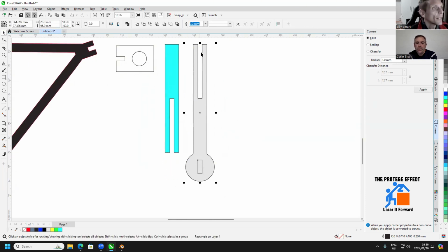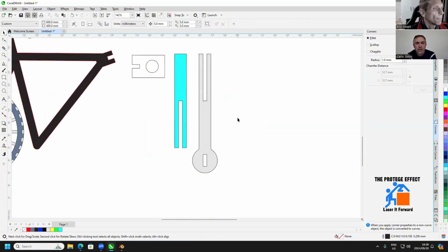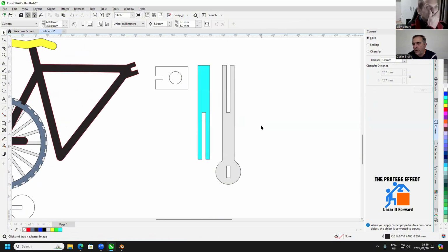Yeah. Billy, can I stop you there quickly? We've just got a quick question on the nudge factor, how you set that. Can you just quickly show when you click on the canvas, your nudge factor comes on? Right, so when you hit escape and you've got no commands active, up here on the top where I'm hovering my mouse, you'll see there's a little button called nudge distance. In here, you can set it to any amount you want.